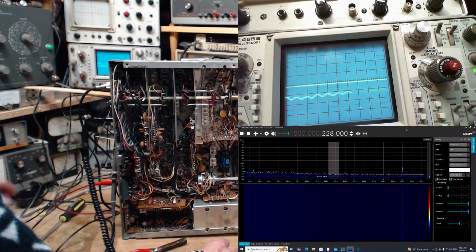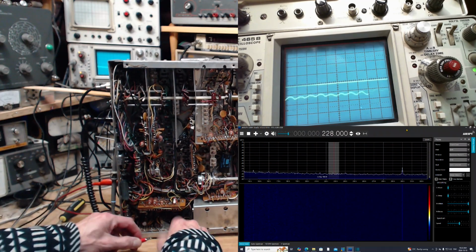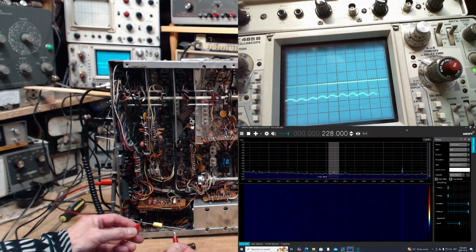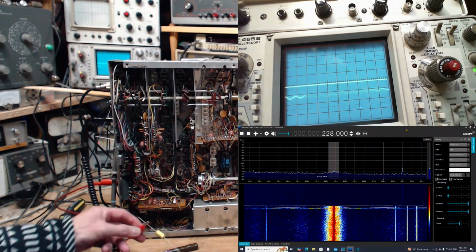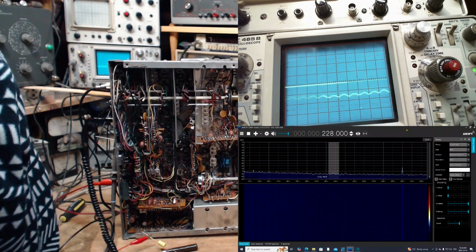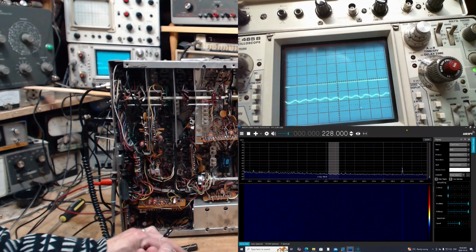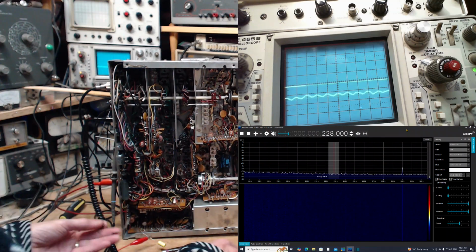So patting that down. Want to stick a capacitor in there? Is that going to do it? I take this off here, and this is too big a capacitor. It's not going to pad anything down. It's just a little much for my SDR. Let me get a much smaller capacitor. I'm sure I've got some laying around here. I don't know if these are really much smaller. Hey, here's a guy with a resistor on him. Beautiful. That's got an orange third band, so it's a K.